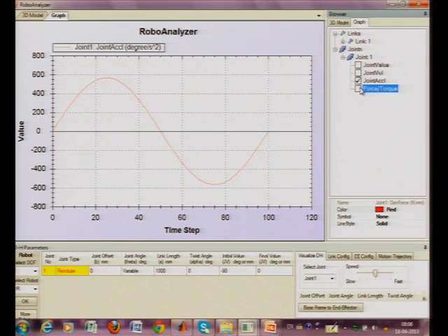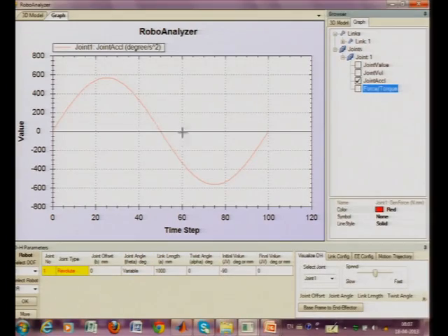We know the inertia about the axis of rotation is m l square by 3, multiplied by theta double dot, will be the torque, because gravity I am now making 0. So, that is why this proportionality is coming. As soon as I add gravity, the gravity term distorts this torque plot, as we have seen in the previous results.